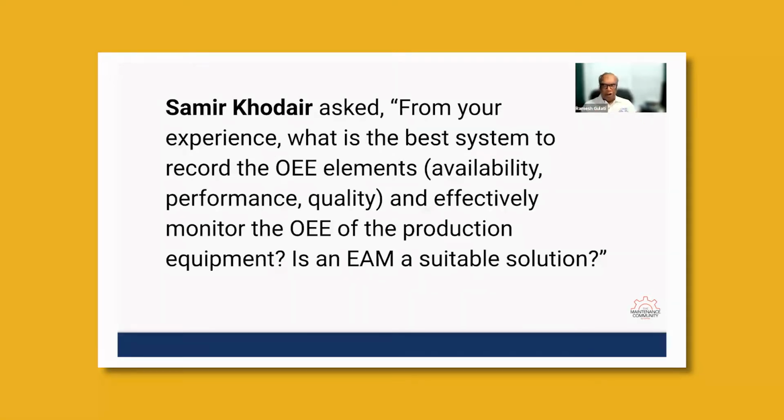We know OEE has three major component factors: availability, performance, and quality. What's availability? Availability is uptime and downtime. So we need to go and get that data. Where is the machine uptime coming from? Where is the downtime? We need to know that. Same thing, you have to think about the performance level, and also your quality, where the scrap rates are. All these data points should be available to you. I don't care if they are in this system or that system, as long as I can pull them out easily and don't have to hunt for them. Then I can make the calculation.